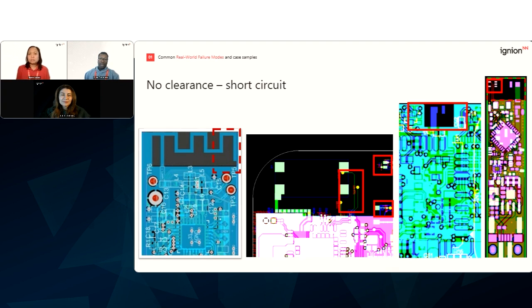But if you look at the first red triangle, you can see some traces that are in your keep out area. Those little traces are going to impact performance. In fact, they should not be there. All traces and any other metal components should lie on the ground plane, on the PCB itself, not in the clearance area.